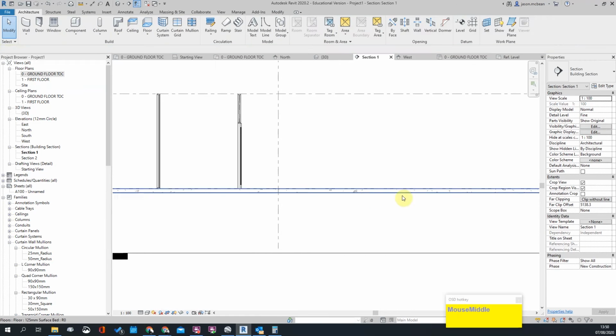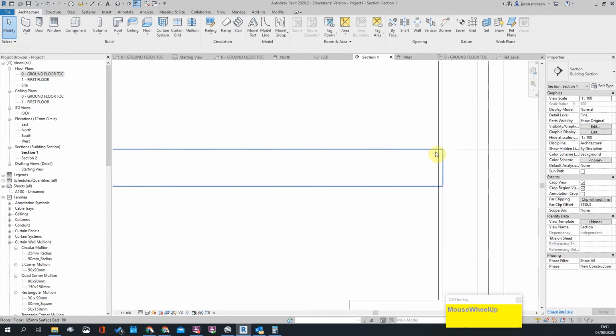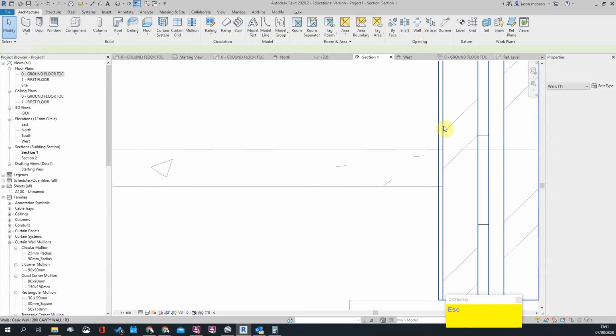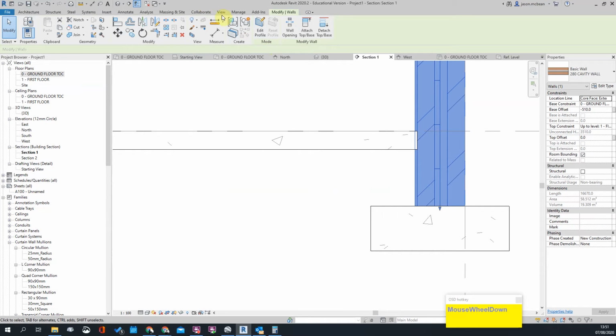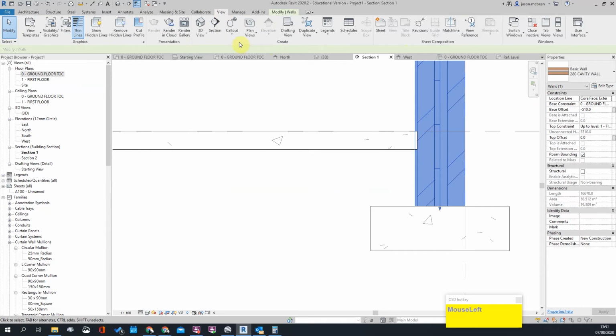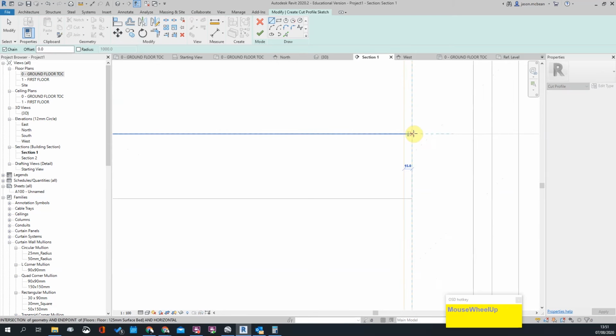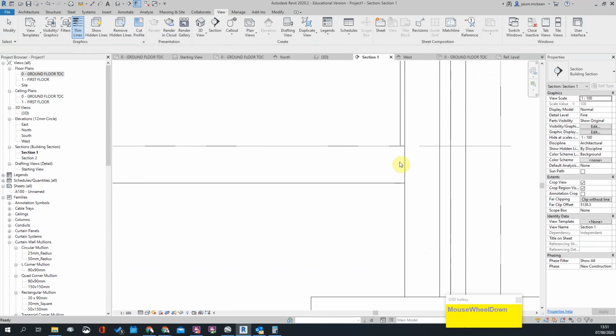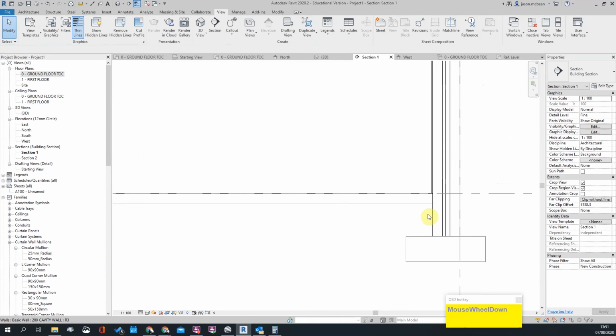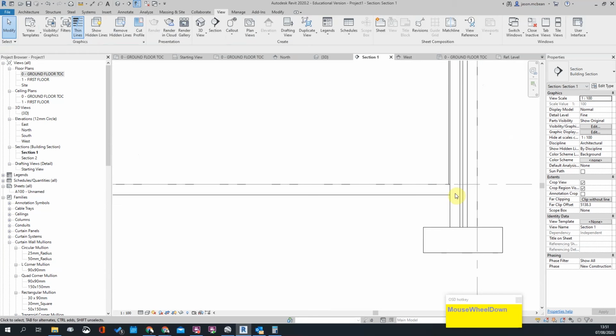Okay, likewise here. Here I haven't fixed that wall with that. So let me show you how to do that again. So you can click the wall, you can go to view. And all I did here was I just changed the cut profile. I select this layer, drew a line. Just remember, I'm not removing it from the 3D model. I'm just changing it in 2D. I'm just changing the appearance in 2D. So that's how I get around it.